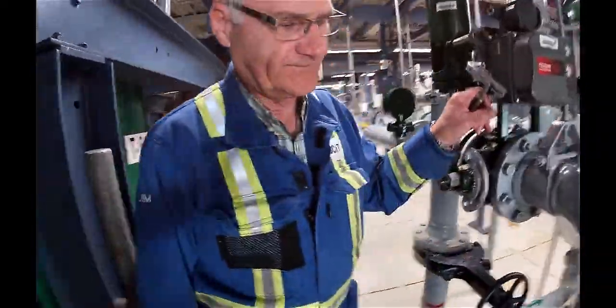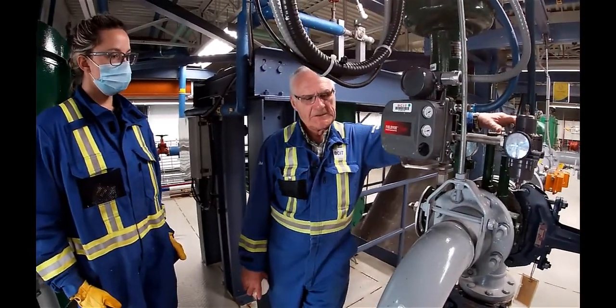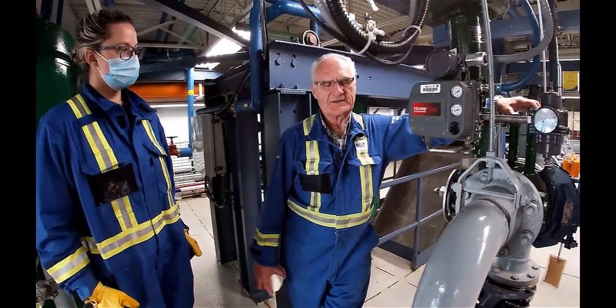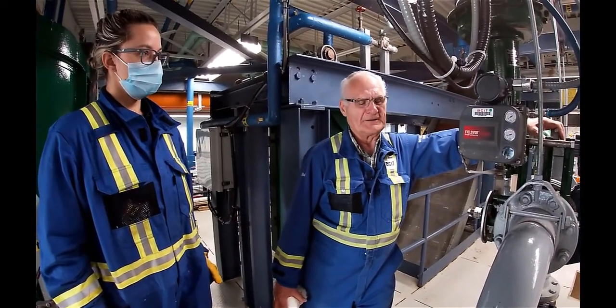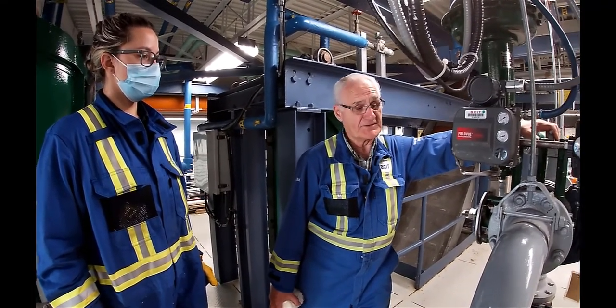Where is Mari? One of the concerns that we have is that when we shut down at night, we've got to make sure that we get all the pulp out of the lines. If we don't, it could end up hardening in there, and if it did, it could do damage to some of the instruments.